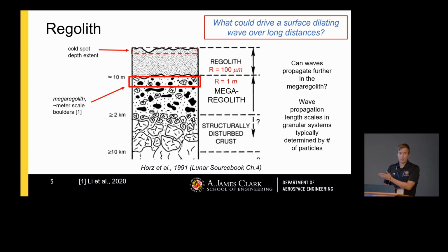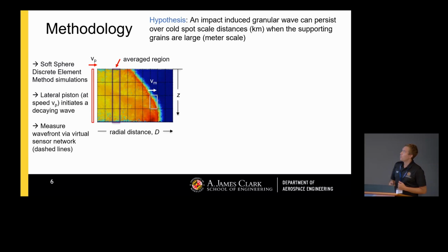But if you have meter-sized boulders, that's 100 meters or something. So, made up numbers. But we'll reuse the same simulation methodology that we had before, but instead of dragging that velocity along the floor, I'm going to use a piston to initiate the wavefront. And so what's going to happen as that wave moves down the channel, the energy in the wavefront is going to decay. And so we're going to measure that by the collisional velocity in the wavefront, or this VM term.